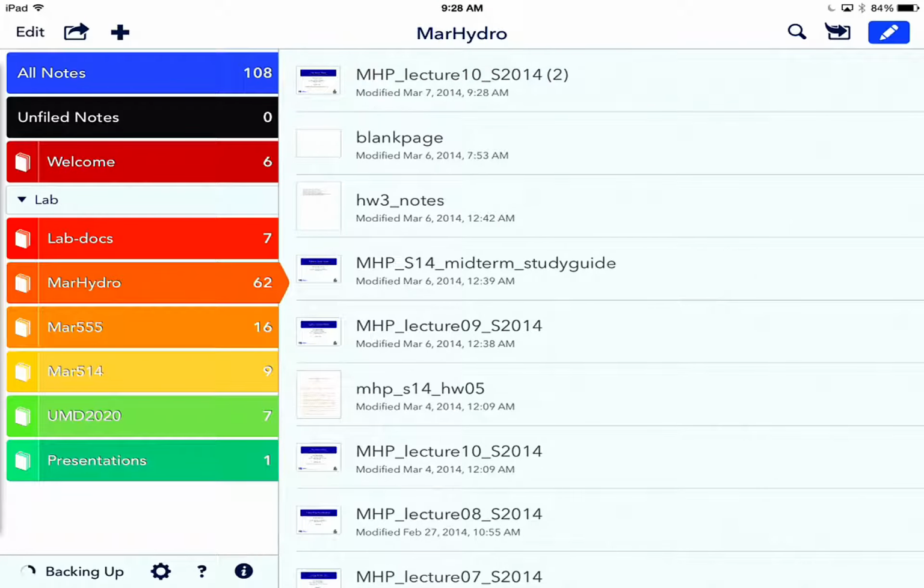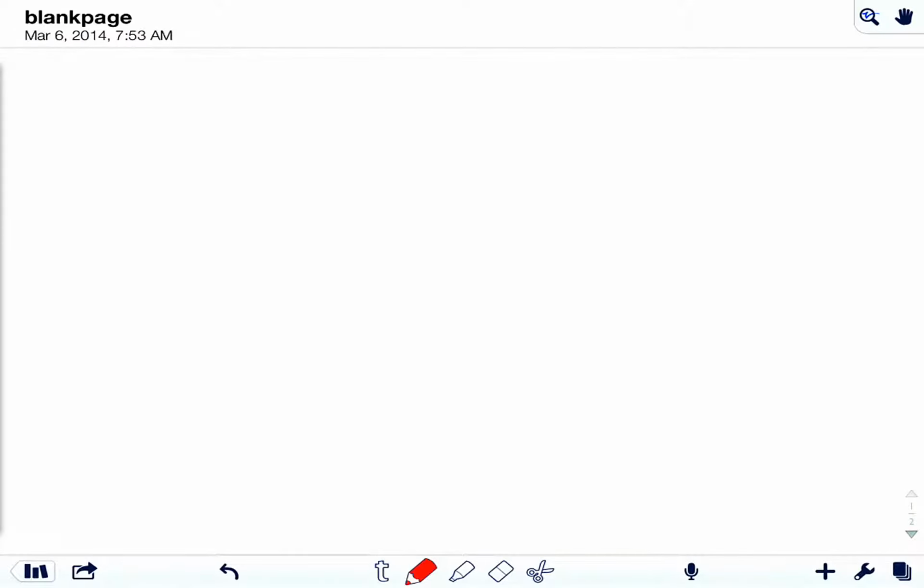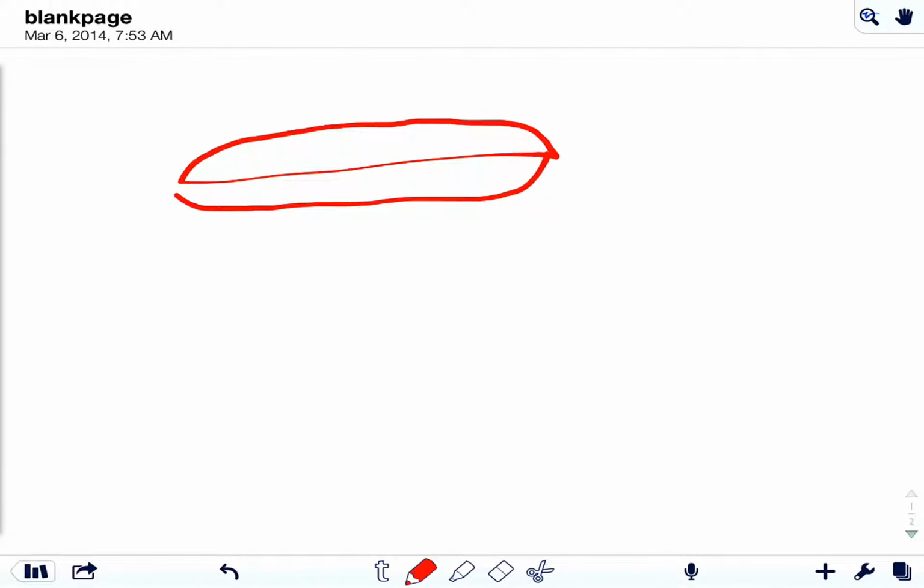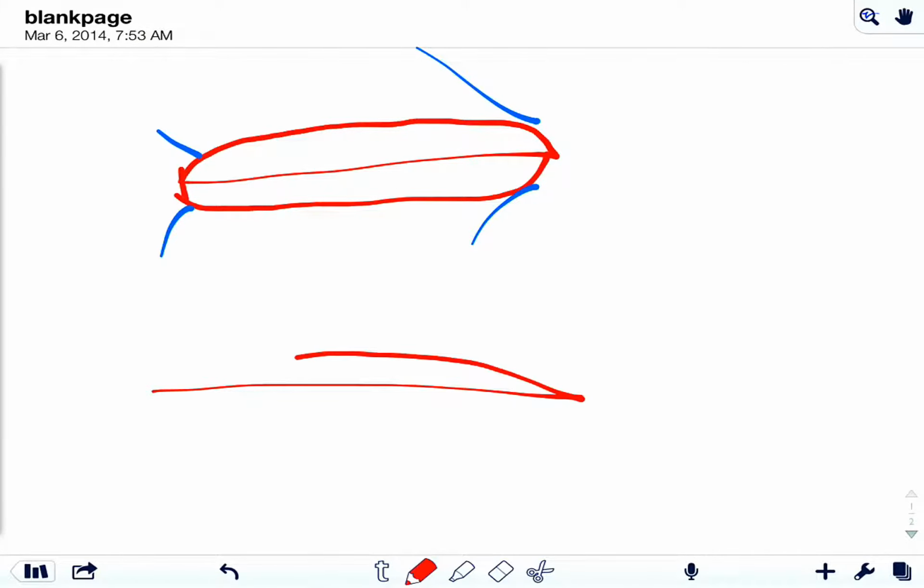Boats that are fuller, I'm going to try to, here's a center line of a boat, a nice full boat. This would be like the water plane of a tanker ship. A full boat will tend to produce an initial bow wave closer to the bow, and the trough will be very close to the stern because it's very bluff. A boat that is more slender, but maybe having the same beam, like a sailboat, is going to produce a bow wave that begins further aft.